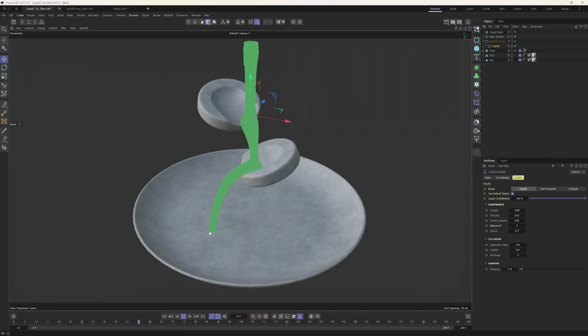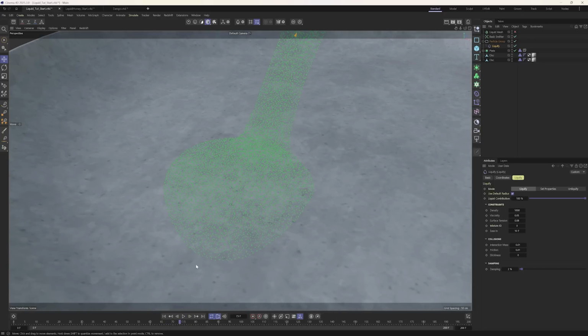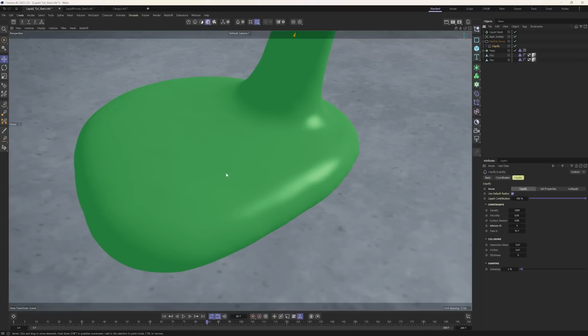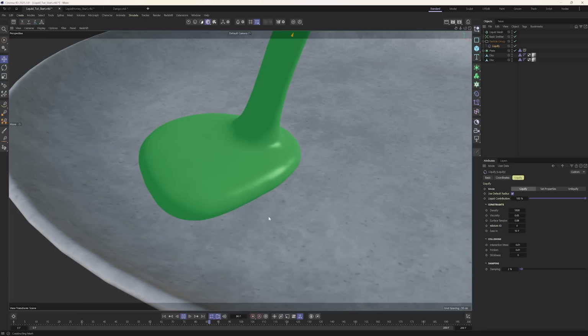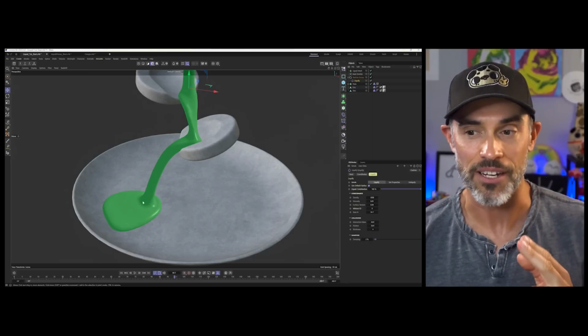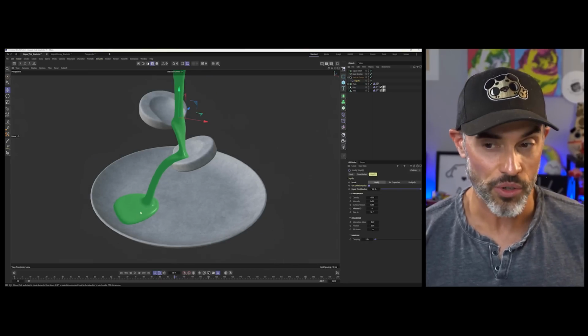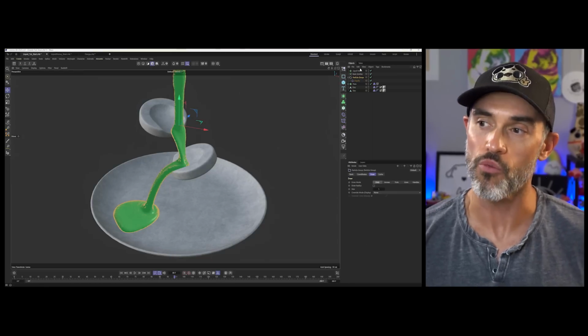And now we can see if we have that jittering, that popping and locking that was going on. If I zoom in to the particle edge where we were seeing that before, you can see that, okay, it's much more calmed down. And if we turn on the liquid mesh, we'll really get a sense of whether this is really popping and locking. And you'd see, no, it's actually very, very smooth, okay? So that is the biggest gotcha of liquid sims. Well, actually the second one, because number one is that, again, it doesn't work at real world scale. So two little gotchas to understand what's going on with the liquid sims.